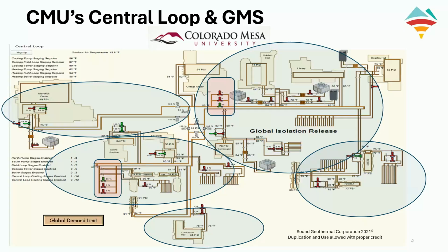District 3 is the Maverick Center. In the center here, we have mixing valves and so forth, so we can direct and redirect the fluid throughout any of the micro districts. Down here, we have a classroom building dorm complex, and we have a second pumping station. These two pumping stations, by the way, when they're used together, are in a kind of parallel series configuration. And most of the time, we only use one or two pumps to start with.